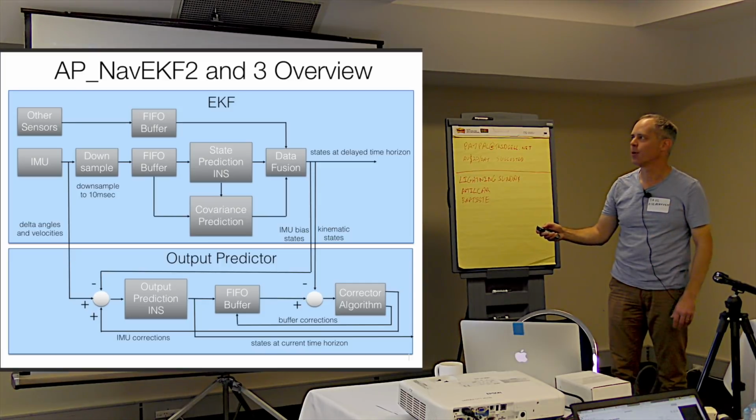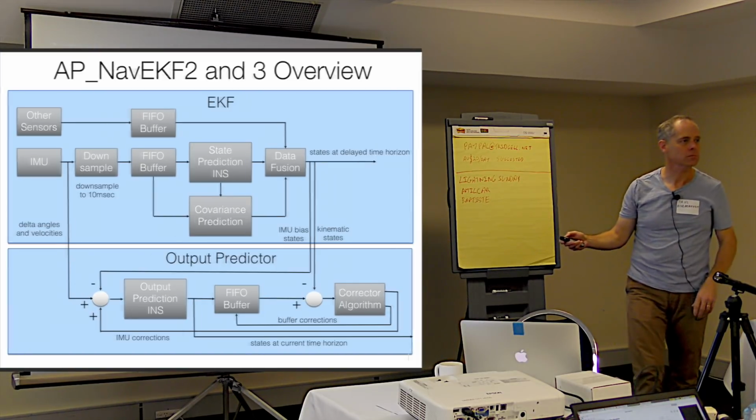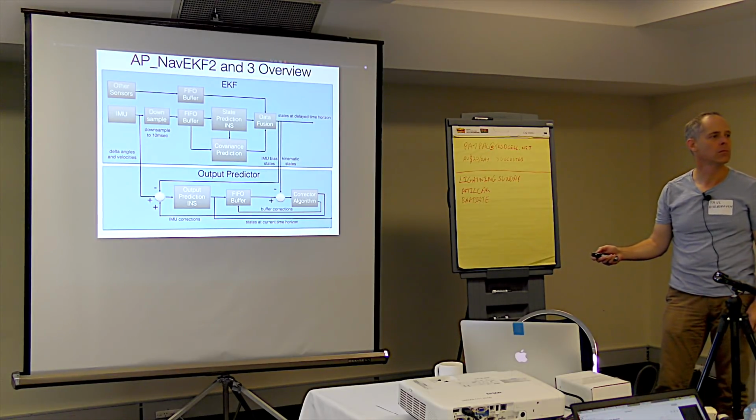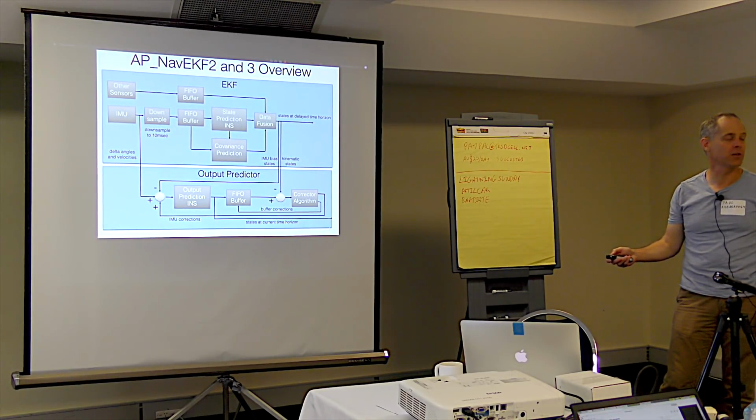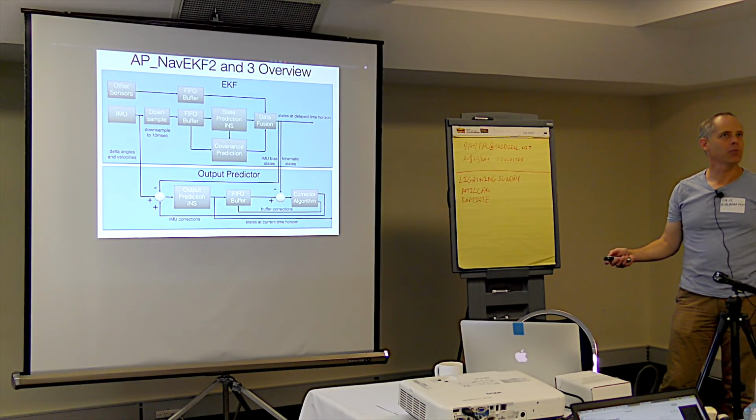Okay, something to remember. Once again, the maximum lag we can have from the other sensors is 1/4 of a second, right? Yes, that's the length of the buffer at the moment. That's what you can tolerate, up to 1/4 of a second of delay. So if there's higher lag and the data is coming in, what will happen? It will get to the data eventually, but it will end up falling out of the window and then the data won't be used.